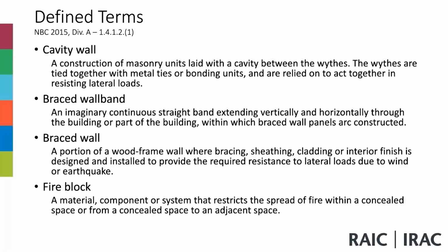Cavity wall, a construction of masonry units laid with a cavity between the wythes. The wythes are tied together with metal ties or bonding units and are relied on to act together in resisting lateral loads. So as we see, like wind loads or seismic loads.